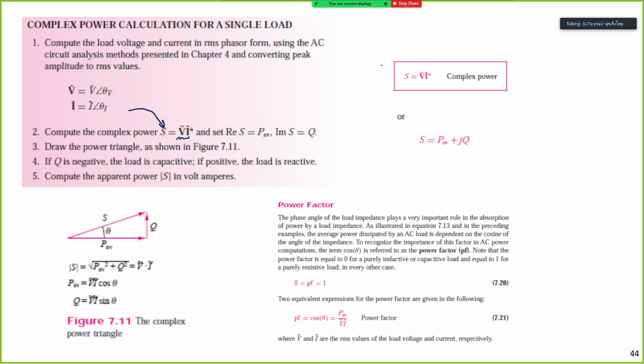What is meant by power with a real and imaginary part? It's not only a real part. What is the physical meaning of the power with an imaginary part, right? So S is V into I. So it will be absolute V and absolute I with angle theta V plus theta I, right? These two values are multiplied together, so we have the power with a phase angle. So for example, S is here, and this is theta of S, right?